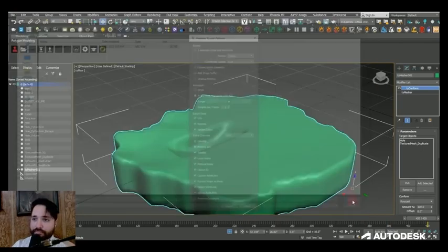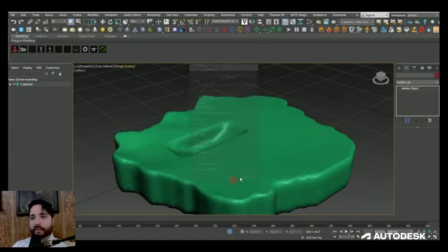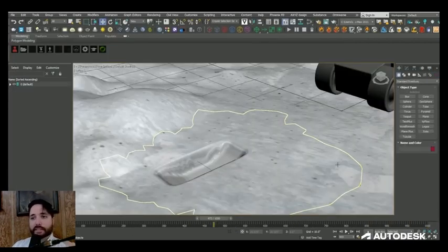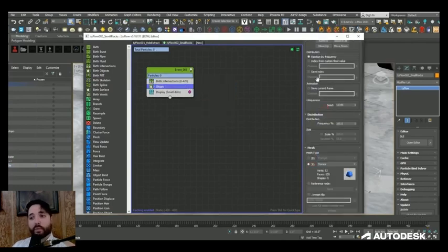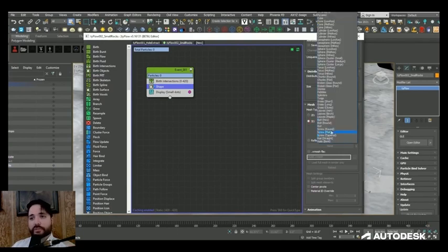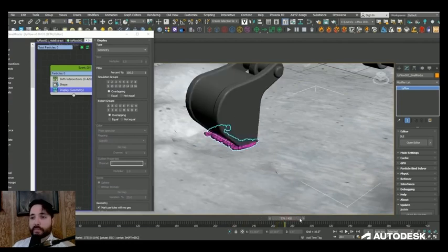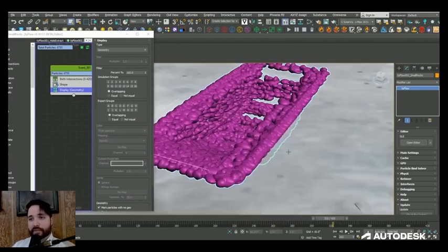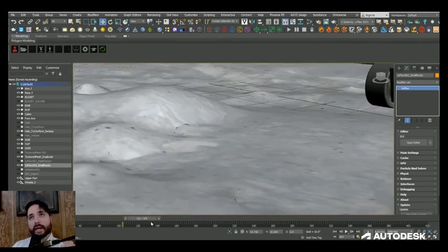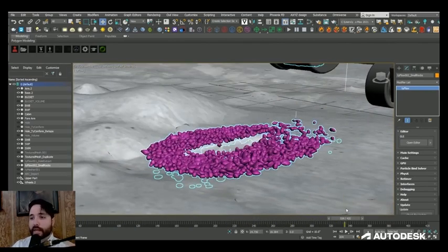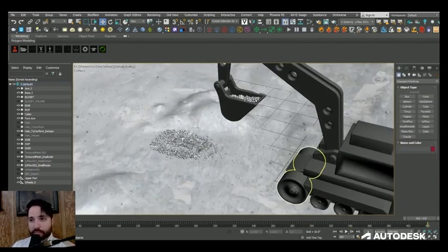UVs on that geometry. For our second TyFlow simulation, I re-imported that exact same Alembic file that I just exported, and I used it as a collision reference so that I could add rocks and other debris interacting with that hole as it's being dug. I just used a birth intersection operator and used some preset pebbles and rocks as the shapes of the particles. Once I was done, I gave the particle shapes collision hulls, and I set up my collision targets so that when I added a gravity force, the rocks would then fall down to the ground as expected. And that's pretty much everything I needed to complete my actual simulation part of this project.